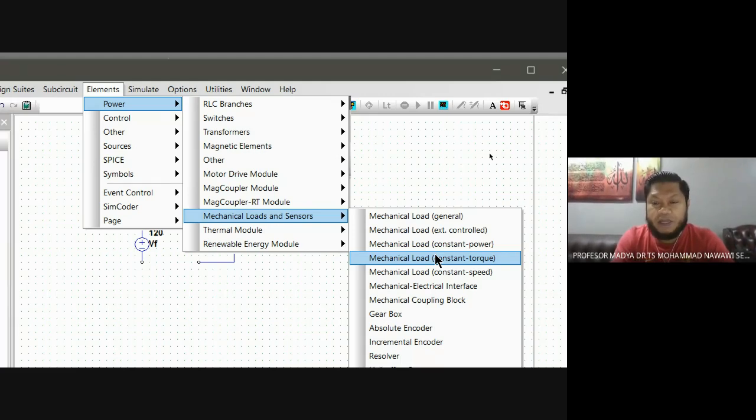So we can actually increase the voltage up to the maximum rated voltage of the motor. So if you want to increase the speed more, you can no longer use the armature voltage control. You have to change to field control, to reduce the field winding so that you can increase the speed further, right?